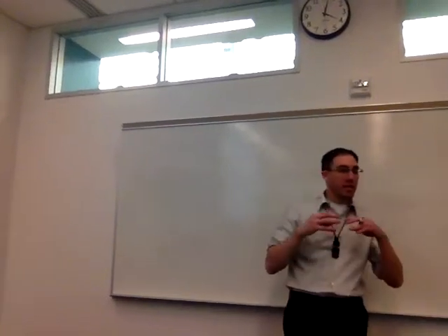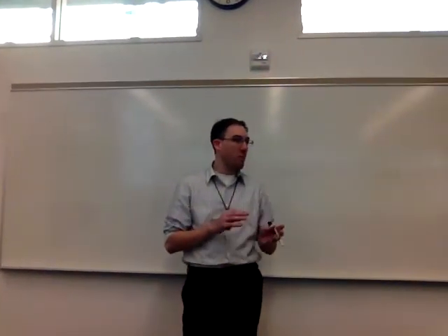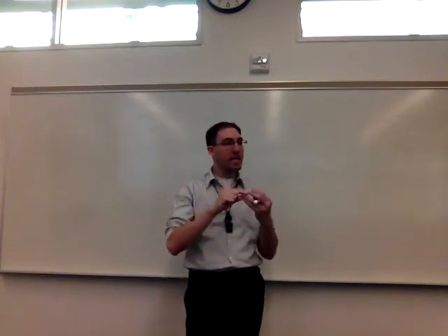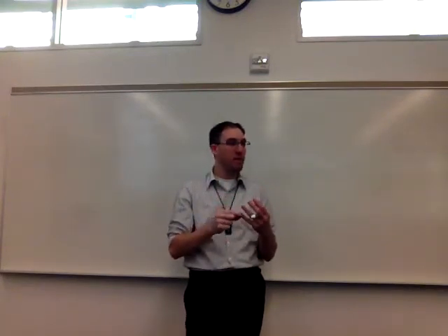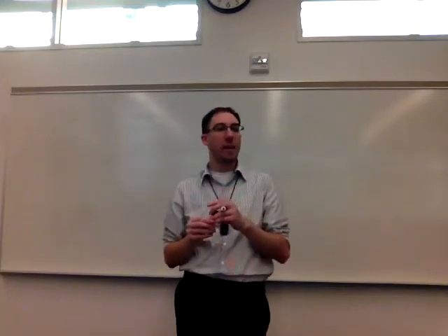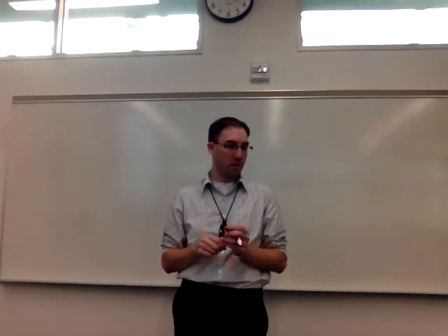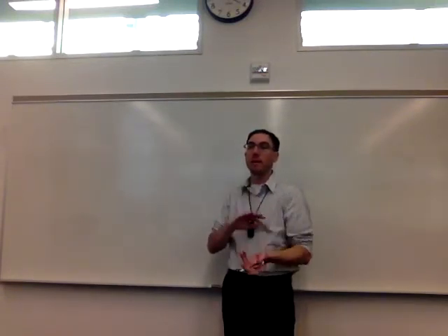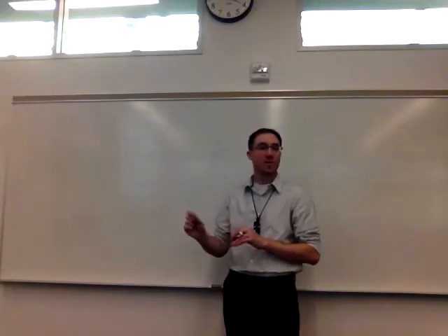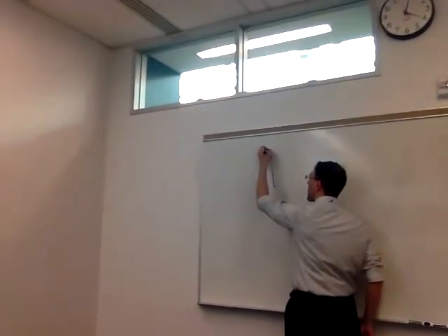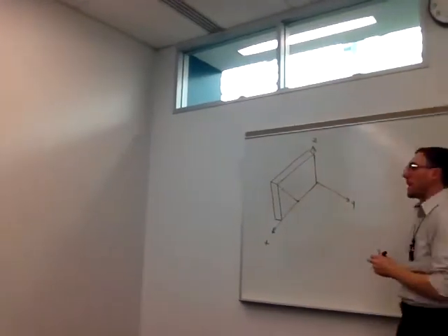The rule of making the subshapes that we didn't have to worry about in the last example, but we do here, is that the subshape should be an easy to calculate shape for its, in this case, volume and centroid. But additionally, each shape should only be made of a single material. So we can't just take the entire rectangular solid because it's made of steel and brass. We still have to break it up into multiple shapes so that each one only has that single material to it.